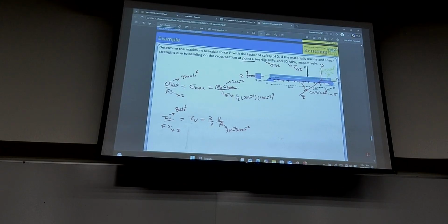You're writing this down. This problem is very applied again. For instance, for mini baja, look at the two ends as the tires, and the load P could come from the weight of the driver or all the components of the car applied at that center, let's say, that centroid.